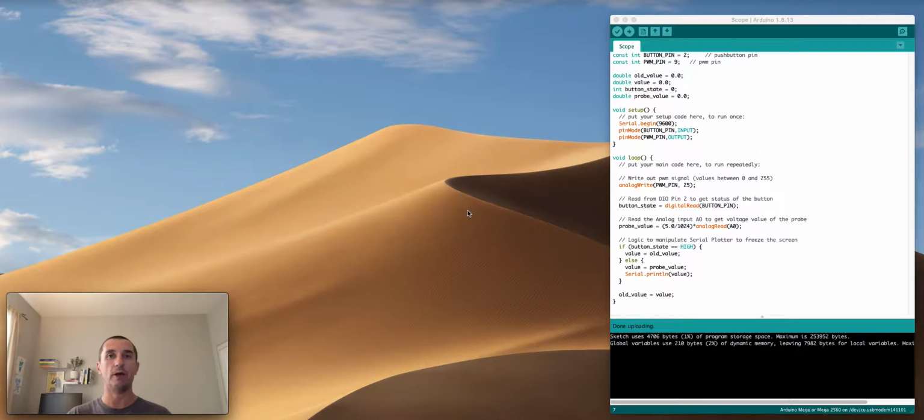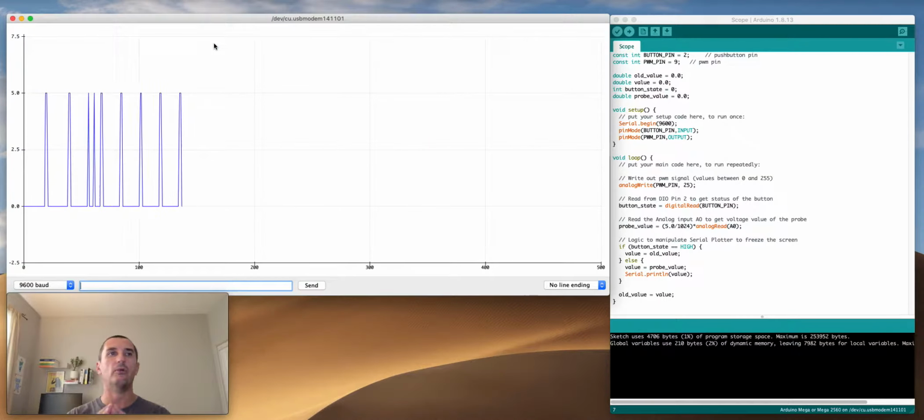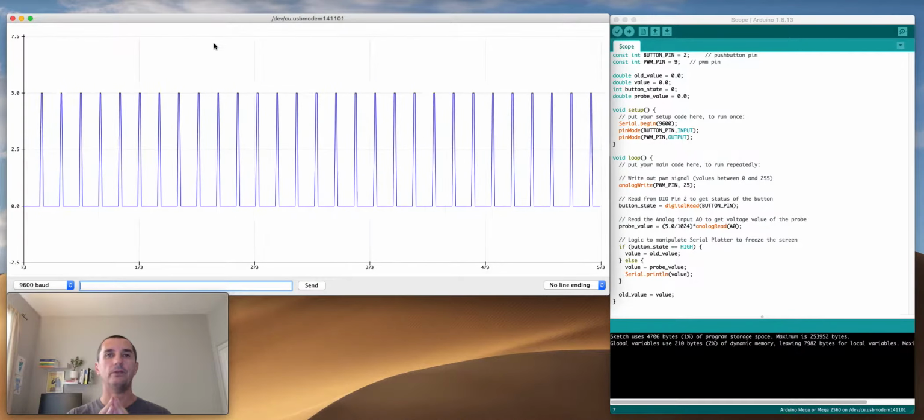onto your computer monitor. To do this, we're going to use the serial plotter that's available within the Arduino IDE. So I want to first walk you through how to load the serial plotter, and that is under the Tools menu of the Arduino IDE, and then look for serial plotter. Another thing you can do is on the Mac, it is Command-Shift-L. And when you type Command-Shift-L, it'll bring up the serial plotter.